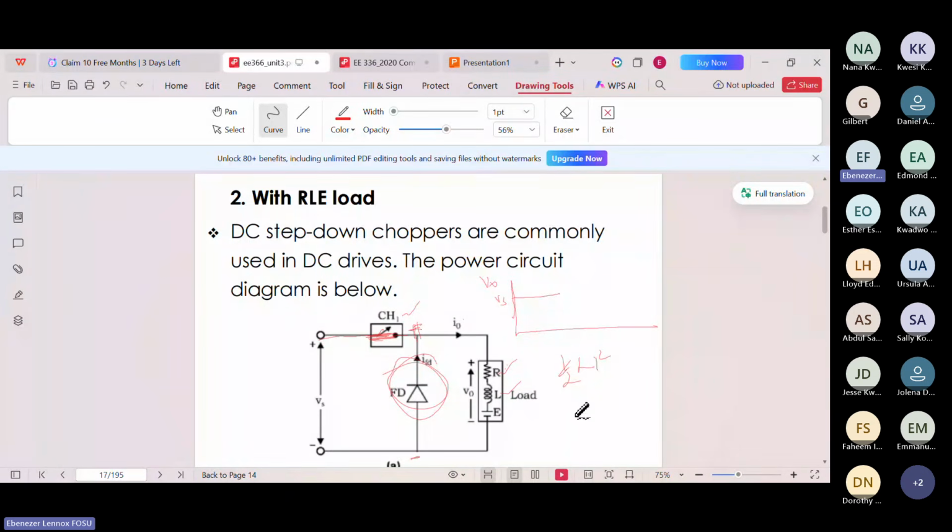So the voltage of the inductor reverses its polarity. This is the voltage across the inductor. Realize that the change in current is now negative, so this voltage is going to be negative. That is now acting like the source, so it's producing the current.